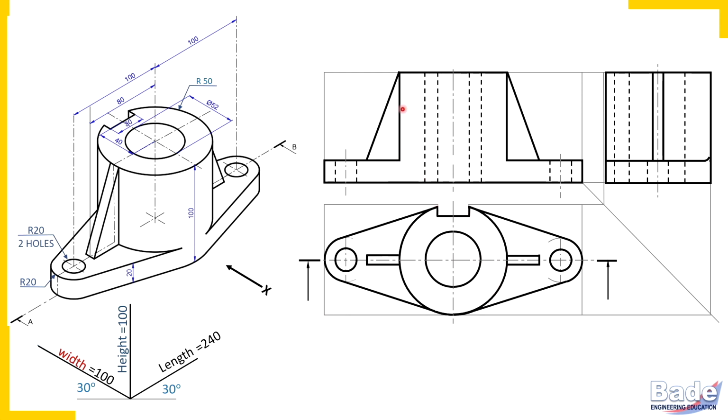Remember, in sectional view, the boundary between the two parts which are attached to each other or which are in contact, for example here, this is cylinder and base plate. Now this edge here I have erased, I have removed. In sectional views, the two portions which are in contact, for example here cylinder and the base plate, the boundary between the two will not appear.